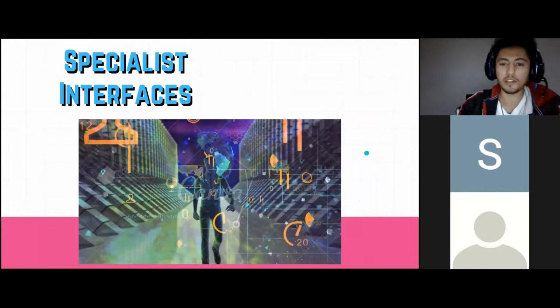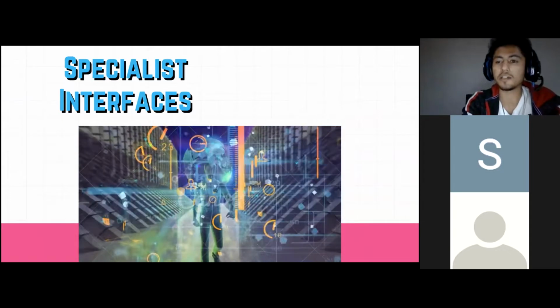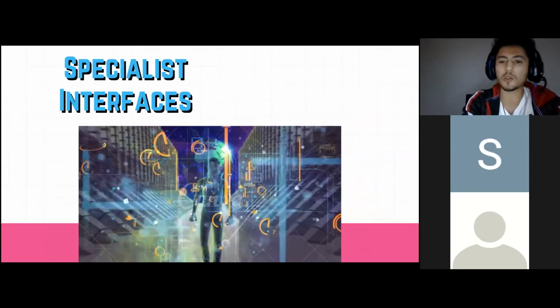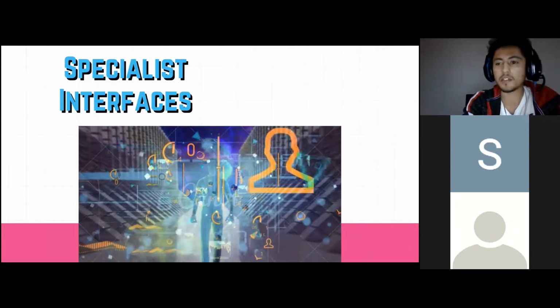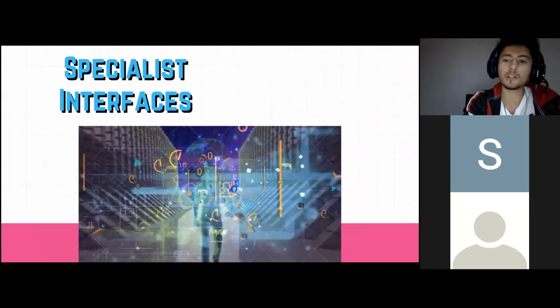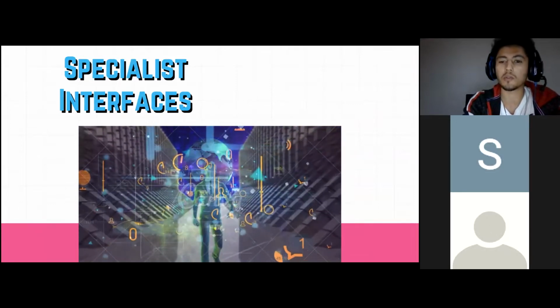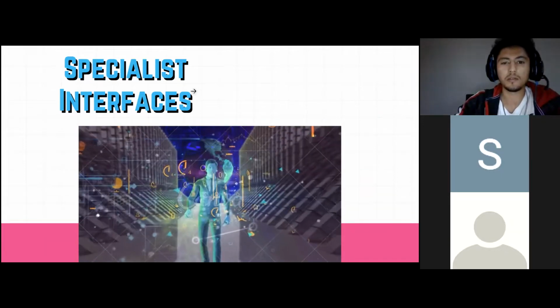Special interface. A special interface application is arc welding, requiring several analog and digital signals to control the welding power supply and filler wire feed drives. These are often available as standard sets from the robot vendors, with special instructions within the robot programming language to control them in an application-specific manner.